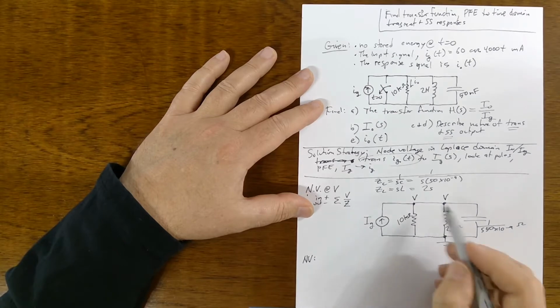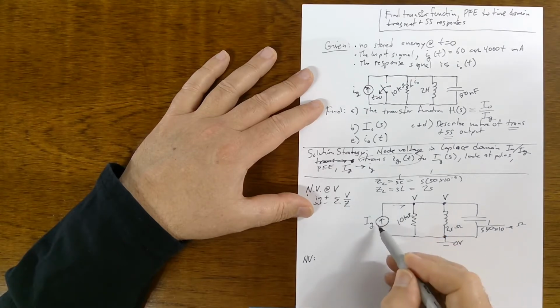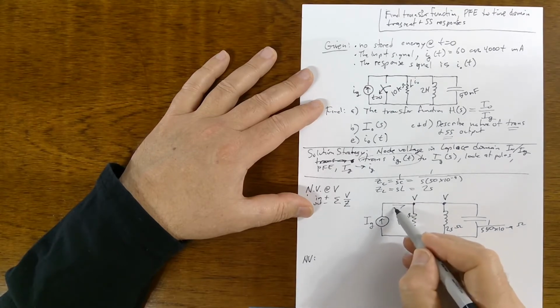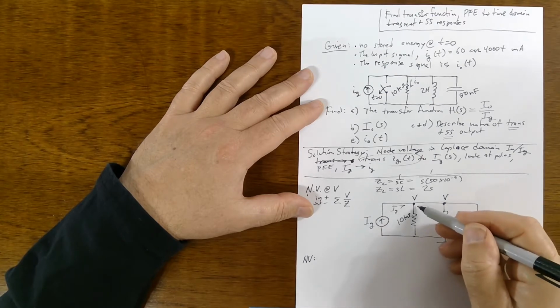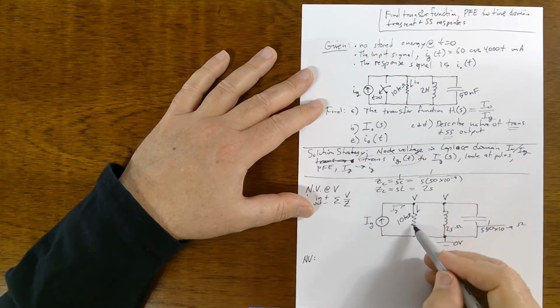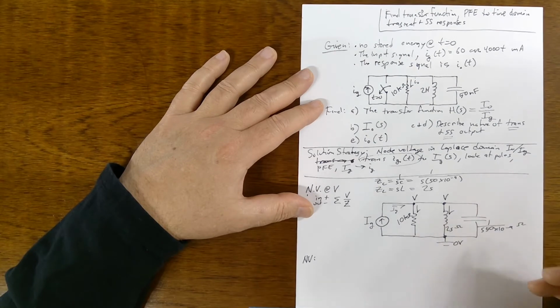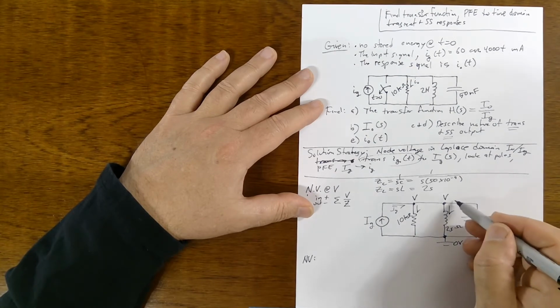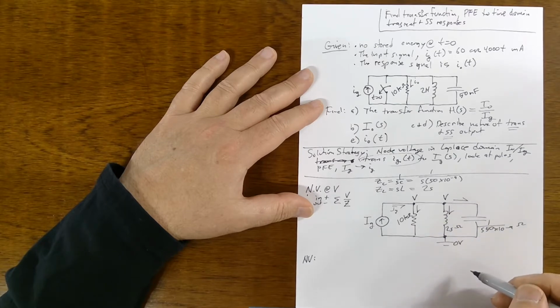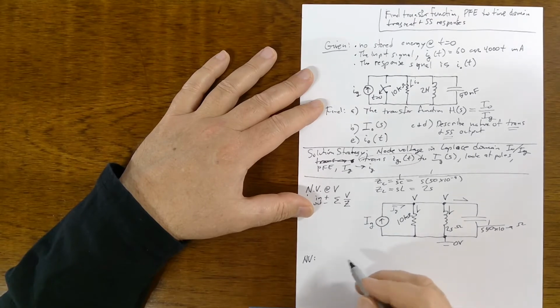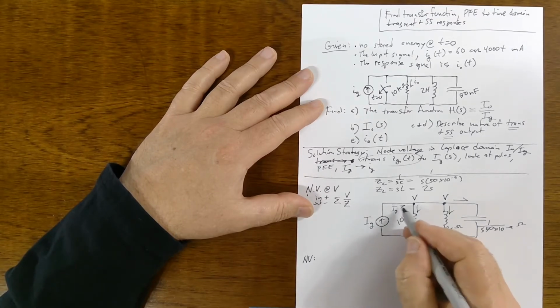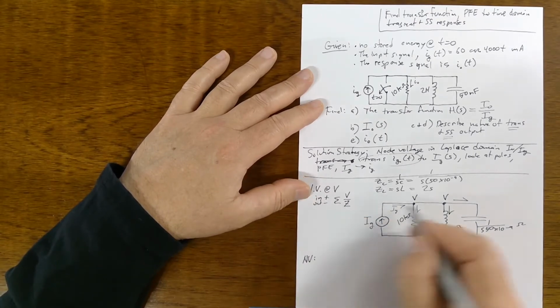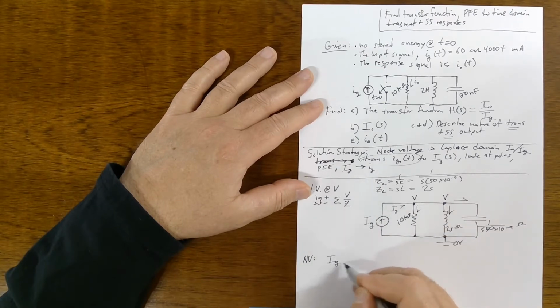The node voltage equation is going to be, okay, so we have to guess some current. This one we'll just go with IG, right here. And then we'll guess that there's one coming out of the V node, and one coming out of the V node that way, and one coming out that way. So the summing in is positive, so IG is coming in, and the other three are coming out, so they're all going to be negative.